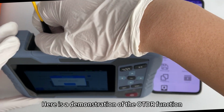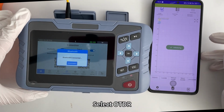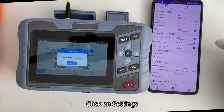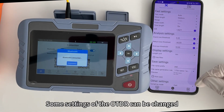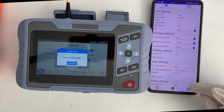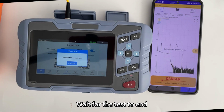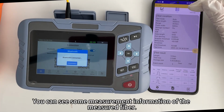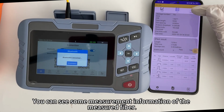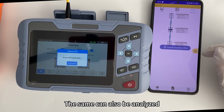Here is a demonstration of the OTDR function. Select OTDR. Click on Settings. Some settings of the OTDR can be changed. Waiting for the test to end, you can see some measurement information of the measured fiber and the event mapping function. The same can also be analyzed.